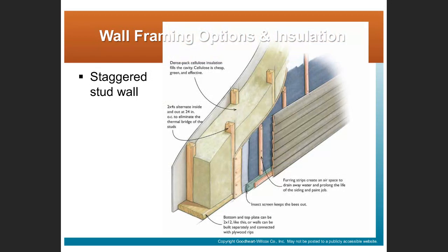Right, again, here's another example of a staggered stud wall. We can make that wall thicker. As we make the wall thicker, we are giving ourselves more space for insulation and improving the thermal performance of that wall.